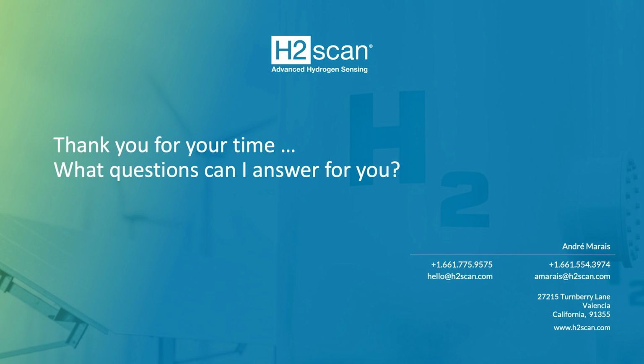It can. Again, it depends. It does depend on the nature of how much gas was generated, and it does depend on how freely your transformer is breathing. If you've got a crack in a weld, if you've got a breather that's not working well, or a faulty pressure relief device, eventually it will dissipate, especially if it's a low concentration. But on an average transformer, it certainly should be there. It certainly is likely to be there for a much longer duration.